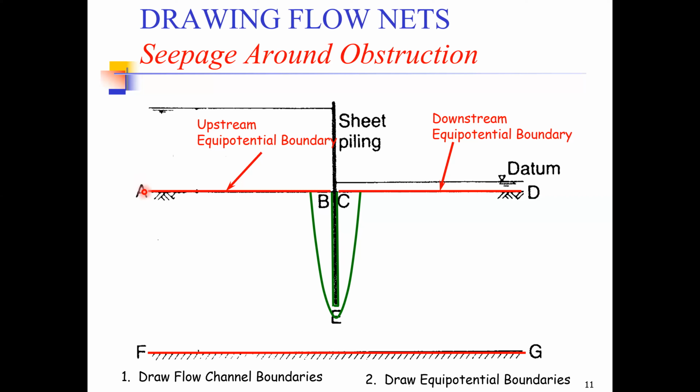So you can see that this was our first equipotential line, and this flow line and also the second flow line, both are making a near 90-degree angle with them, both on the left side and also on the downstream side. Now, if I ask you to draw another equipotential line somewhere over here, how would you draw it? You might have guessed that this is how our equipotential line would look. We can draw a similar equipotential line on the other side as well.